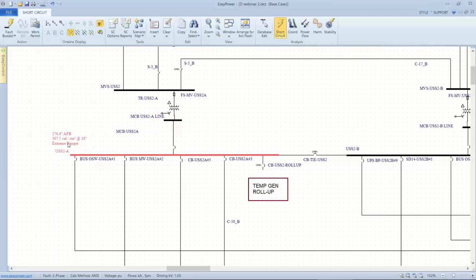Well, it doesn't change this. This still seems out of whack. If we look at our current, the thing that strikes me is this is a very low current, and it could be contributing more instant energy calculation because it's not tripping anything. So let's kind of go back to the arc flash calculations and disable this breaker. And it doesn't seem to change. Just disable this breaker. Now with this breaker open, we have 2 calorie exposure.